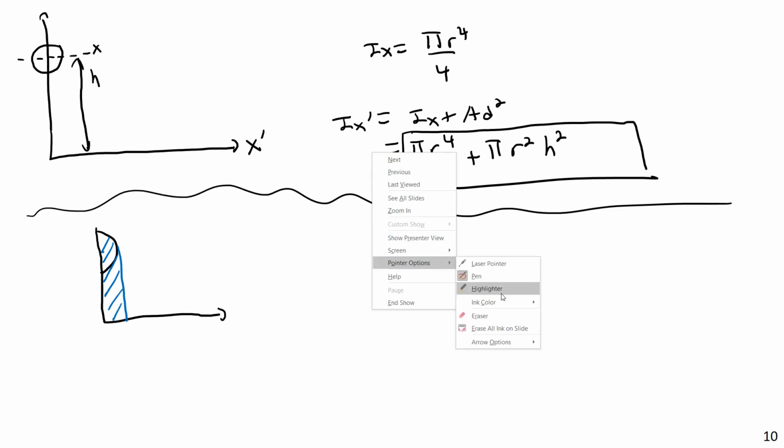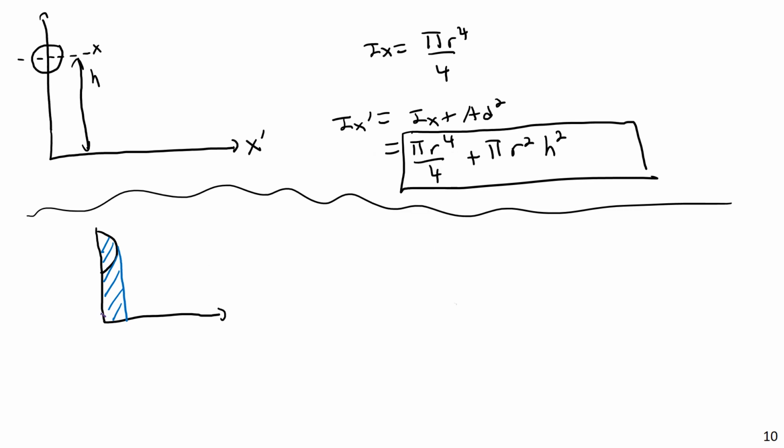Then I would also calculate the moment of inertia of the area in purple here, basically below the lower boundary of the circle. And then, to get the moment of inertia of just the circle, I would take the one from the top boundary of the circle all the way down to the axis and subtract the moment of inertia from the shape below the bottom boundary of the circle.